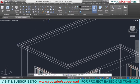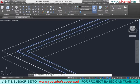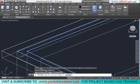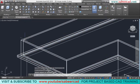Next, I'll go to offset command again and I'll give an offset distance of 10 centimeter, which is the thickness of the parapet wall. I'll select this as the object to offset and this is a side to offset. Next, I'll create the parapet wall by press pulling these two profiles. So I'll just click on the press pull command, or else you can type press pull using the keyboard, and I'll just give a click at the middle of these two profiles. And you can just take the cursor in the upward direction, then you can type the value, which is 90 centimeter. So I typed 90 because that is the height of the parapet wall.